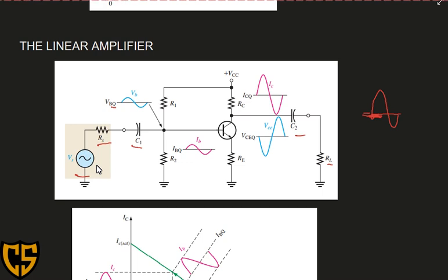So of course, you are aware that the main purpose or the main application of the transistor is amplification. We input only a small current, but when it reaches the output, it is already amplified. So as the sinusoidal collector current increases, the collector voltage decreases.